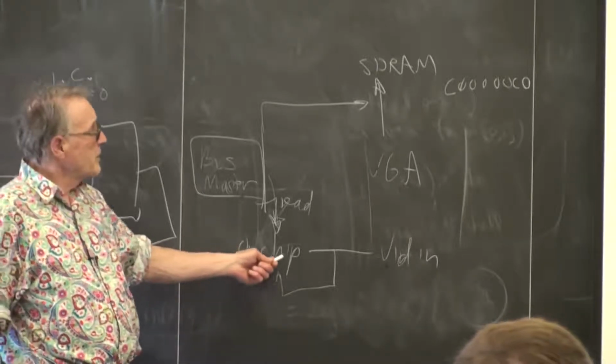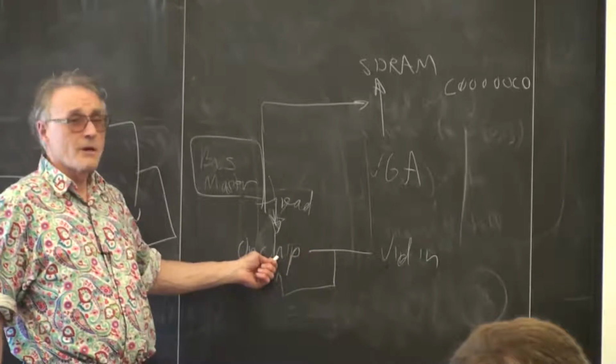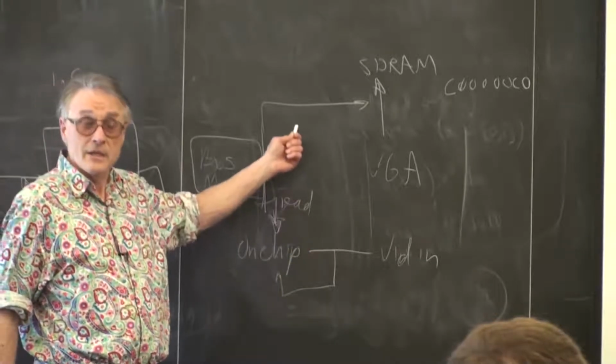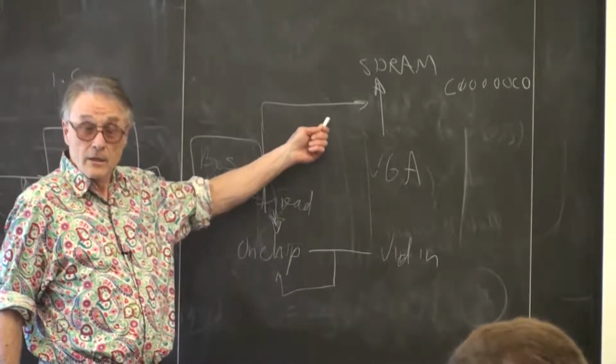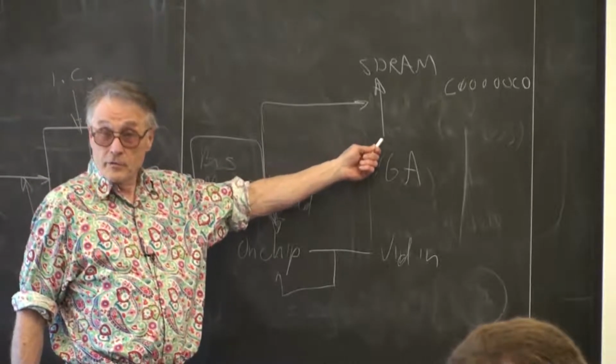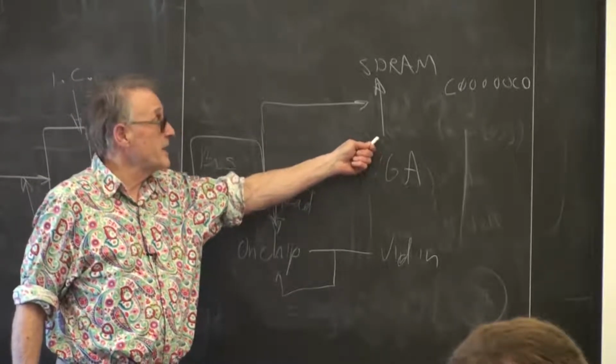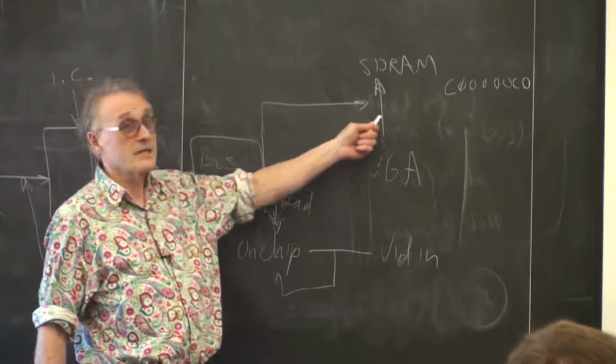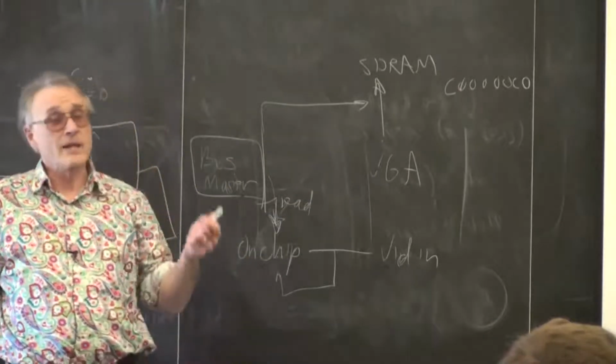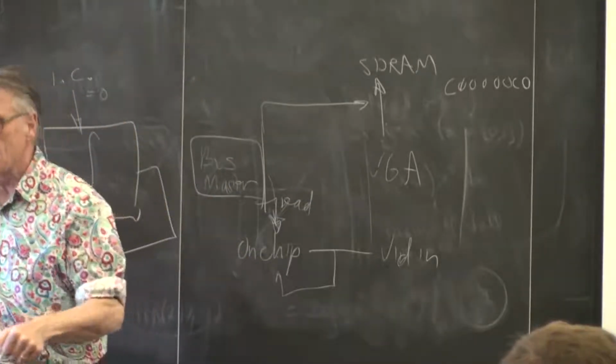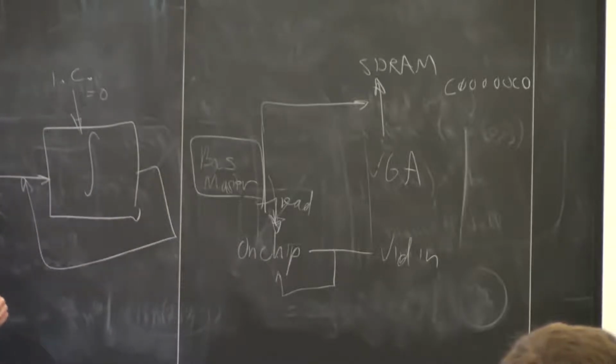If you don't do that, then you have to read the on-chip memory using the HPS, take it over into an array in the HPS, and then send it back across the bus to the SDRAM for display. And that's going to be guaranteed not to do more than 2.5 million pixels a second round trip, which is just barely fast enough. It's fast enough by a few percent to do video. But it's going to take the whole bus bandwidth to do that.